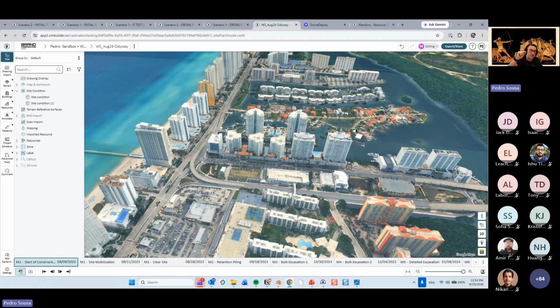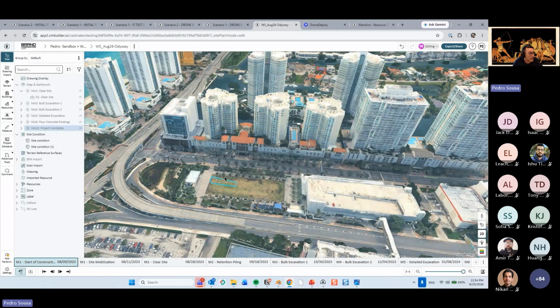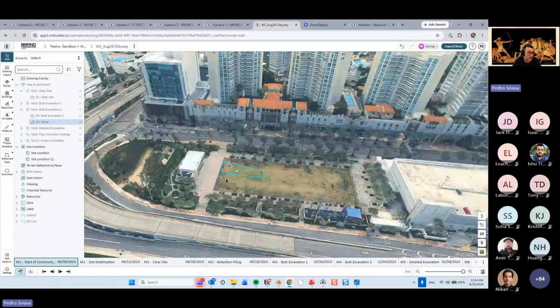I would need to select each one of them to figure out what was generating that. But from this drop down over here, I could select and highlight where these elements were. And then I noticed that one of the operations was not showing any kind of highlights over here. So that was the operation that was causing a problem.